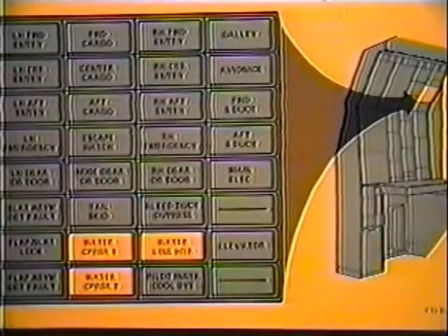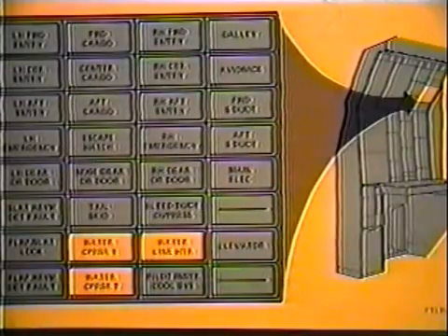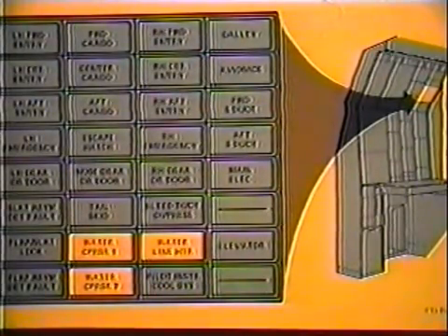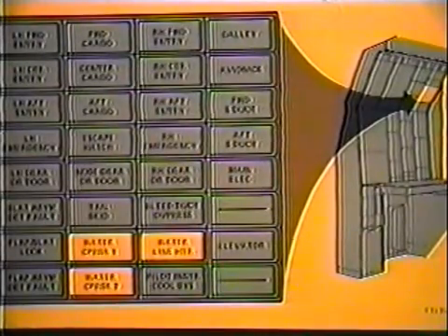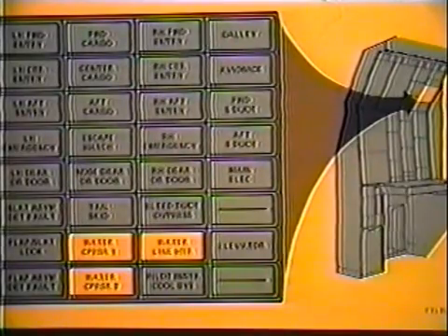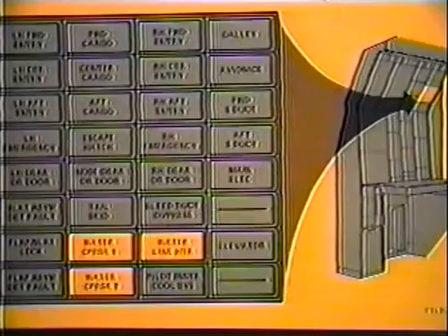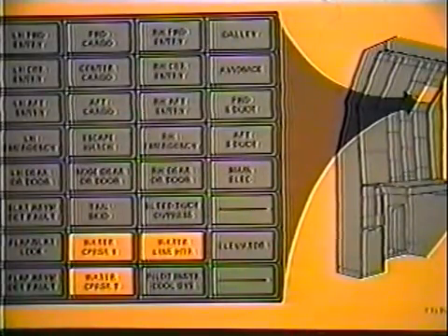Lights associated with the water system are the 2 water compressor lights and the water line heater light on the second officer's annunciator panel. If either water compressor fails, its respective legend will illuminate. If one of the dual-element water line heaters fails, the water line heater light will illuminate.